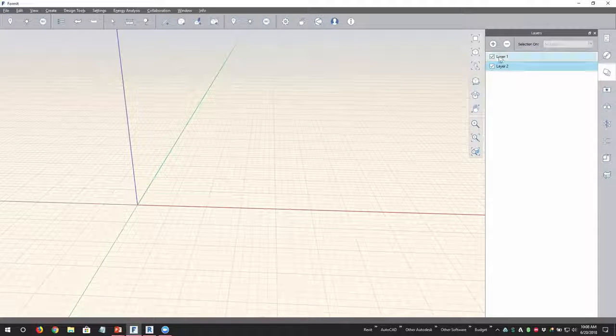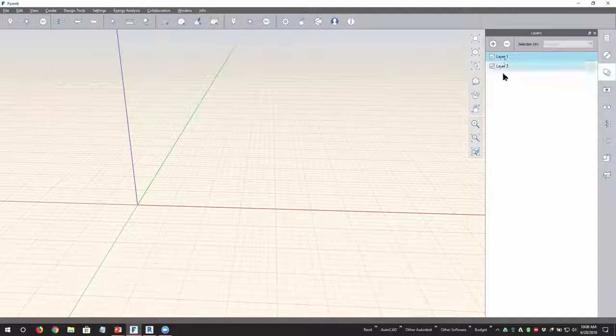So I'm just going to create a couple of levels in here to show, and I can double click on these to give them a name. So here, just Level 1 and Level 2. And when I start to draw my elements, I will be able to use these levels to assign them to an object, and when that gets pushed into Revit, we'll see the levels there.